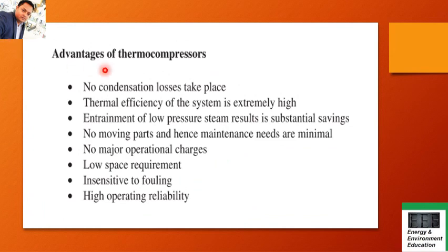And here are a few advantages of the thermocompressor which may be asked in the exam, to explain or briefly list out. So at least you must remember five of them. You can see here the advantages of the thermocompressor. The first one is that no condensation losses take place. Thermal efficiency of the system is extremely high. Entrainment of low pressure steam results in substantial savings. So you are utilizing the low pressure steam here in the thermocompressor. No moving parts and hence maintenance needs are minimal. No major operation charges, low space requirement, insensitive to fouling, high operating reliability. So these are the important points that you must understand and remember as advantages of the thermocompressor. If they ask you in the exam to explain it, you must be able to do it, friends.